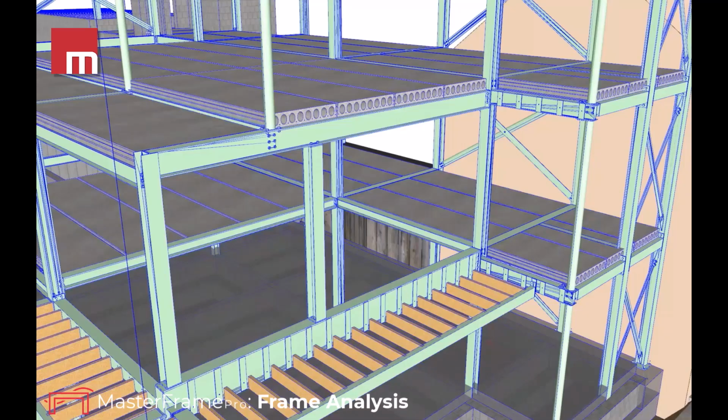And the precast floor slabs, as they are a third-party proprietary product, they're not designed in the software, but they can be applied as gravity panel loads within MasterFrame, along with the associated dead and live loads. And as mentioned previously, the precast slabs here provide diaphragm action for the floor and can be modelled in MasterFrame as a stiff deck with sufficient detailing by the designer using the relevant structural grout or topping details.